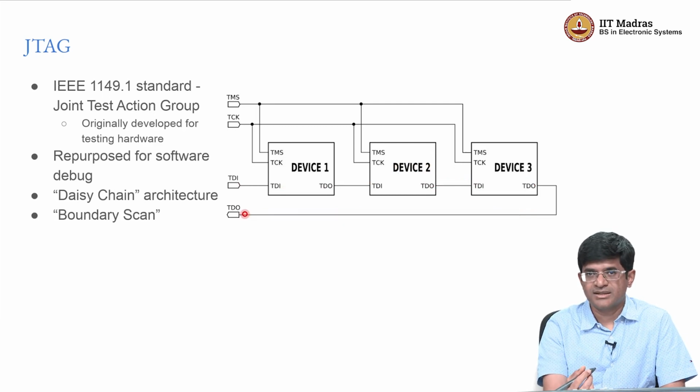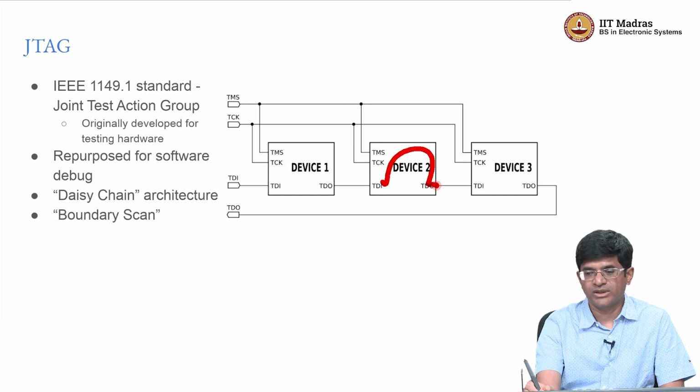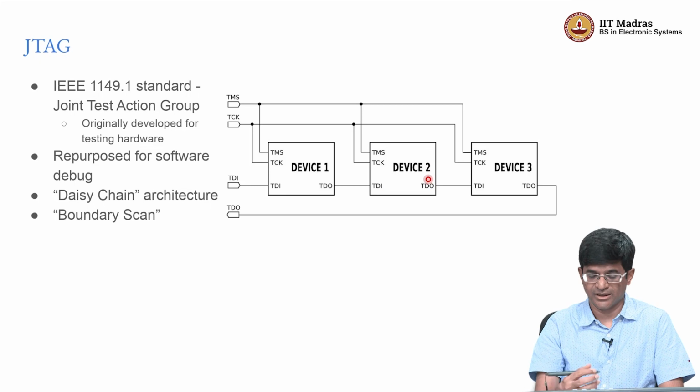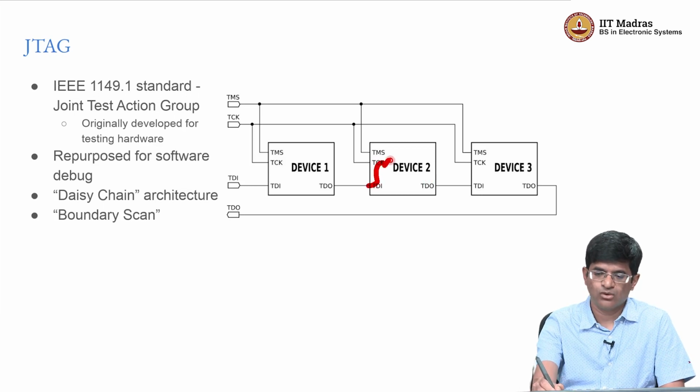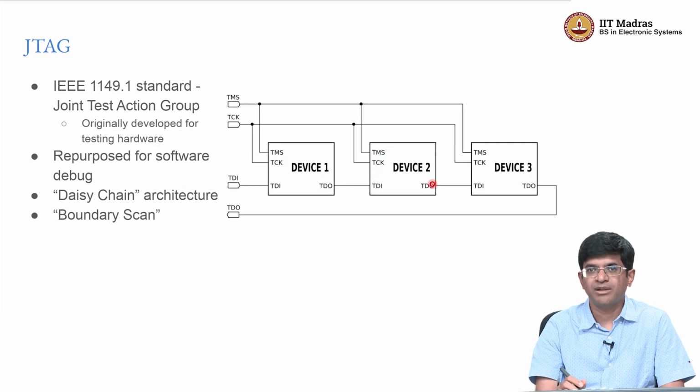Thousands of clock cycles for effectively getting the output corresponding to a single clock on this particular system, right? But it turns out that that's actually still quite useful because it gives you such a detailed level of control over the internal state of the system that you are actually single stepping a piece of hardware directly, which means that even though it is slow and there is extra logic involved in the register construction and so on, it turns out to be a very powerful mechanism for actually testing digital circuits.